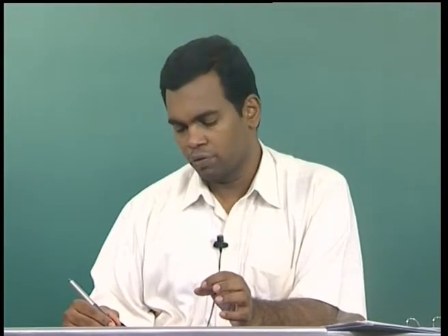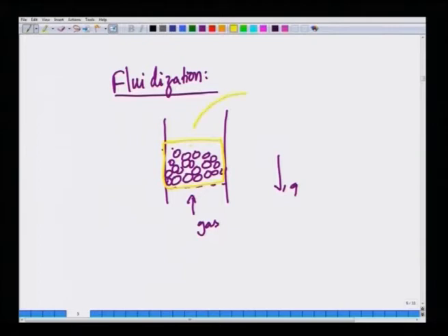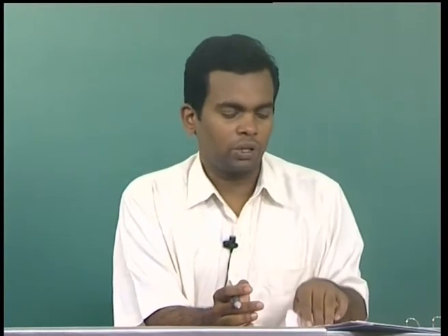Okay. Other design requirements are such that the fluidization should not be such that the particles go out of the bed. Okay. There should not be entrainment of particles outside the bed, because the gas will come in and go out, okay, but when the gas is going out of the bed, it should not take away particles with it. So, we have to worry about those issues as well. So, we will try to address all these issues based on whatever we have done so far.